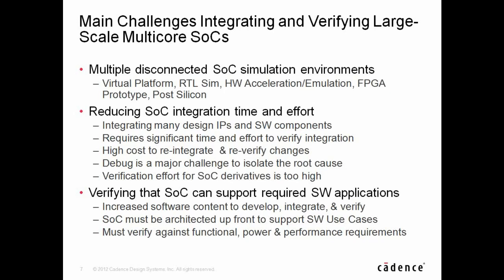FPGA same, right? So that's one of the big challenges we see for SoC integration. If you've not got a smooth flow backwards and forwards across the engines, it's going to fail, right? Or it's going to be much more work to figure out what went wrong in your FPGA, and then go try and reproduce it in simulation. I've already said we're integrating. There's obviously lots of components, and significant time and cost of reintegrating and re-verifying.